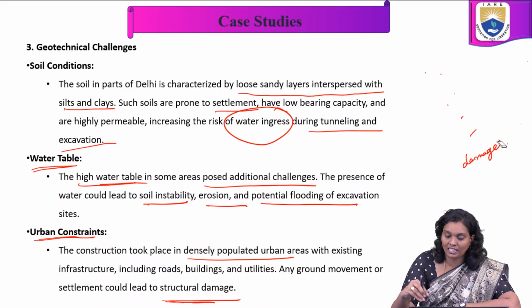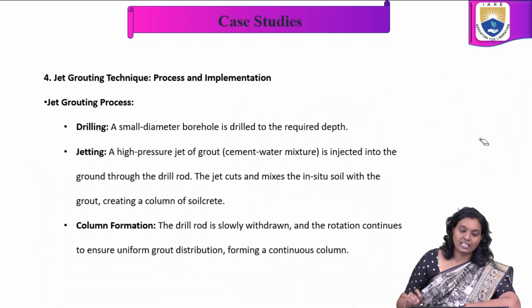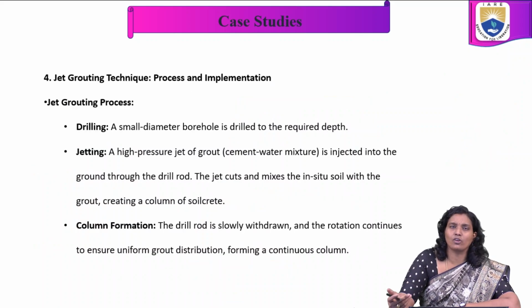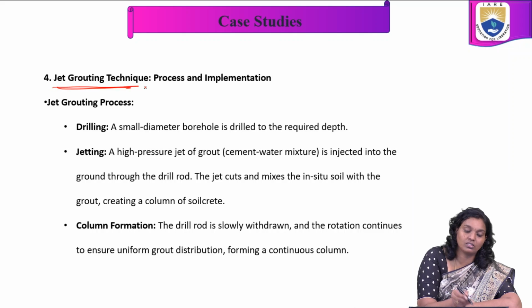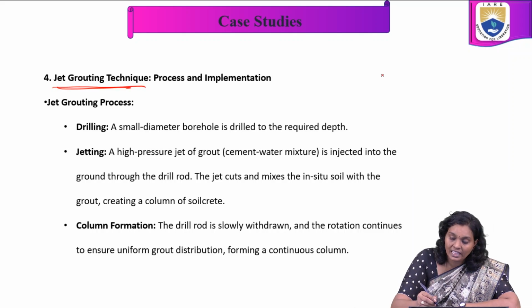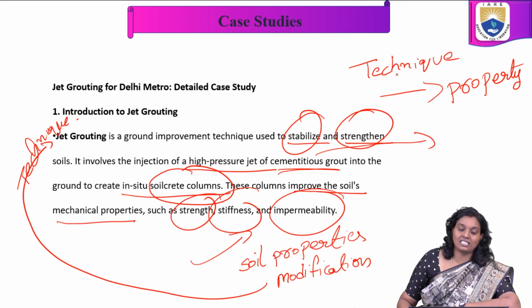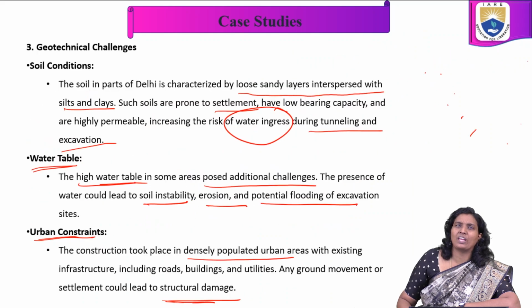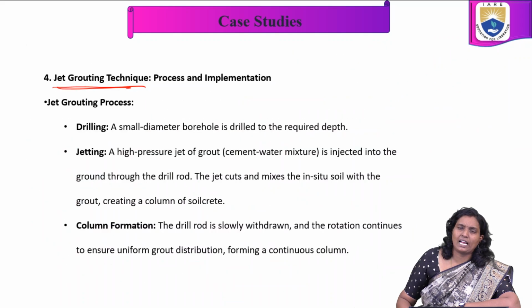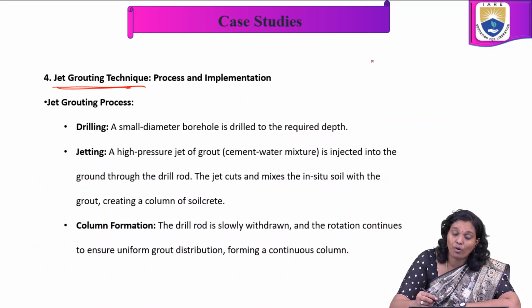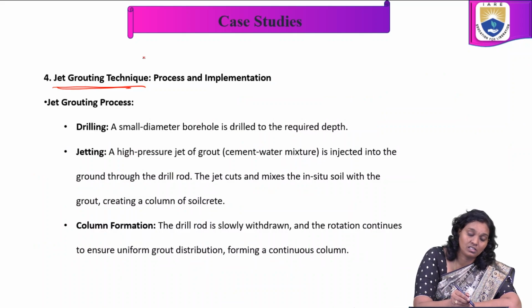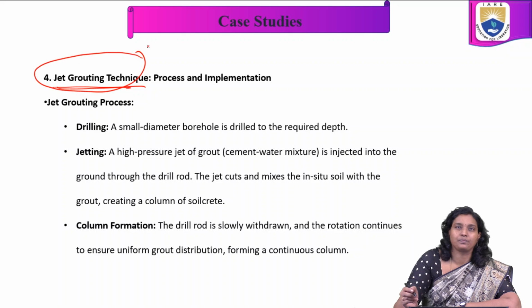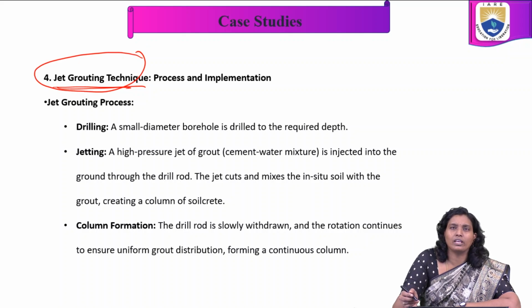For all these characteristics we have to understand in different ways. For this, we are going to implement the jet grouting technique. Based on all these conditions, the overview and the geotechnical challenges, we have to choose which type of technique is suitable, and that is the jet grouting technique we choose. In jet grouting, the process involved, how we implement it, is very important in this particular case study.